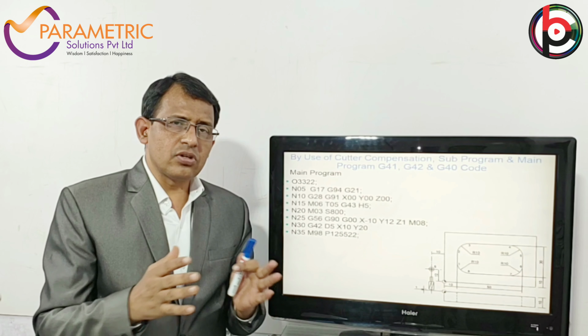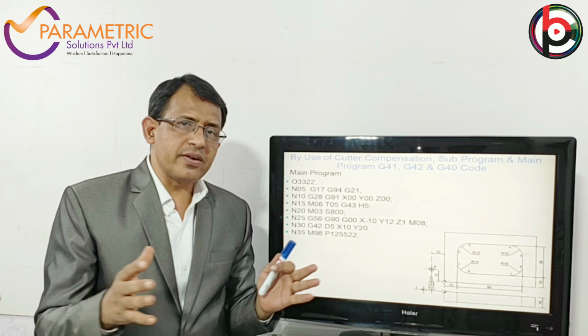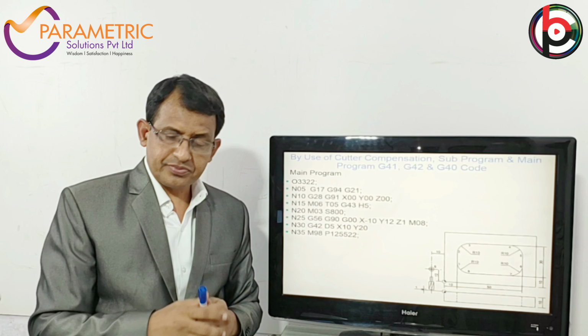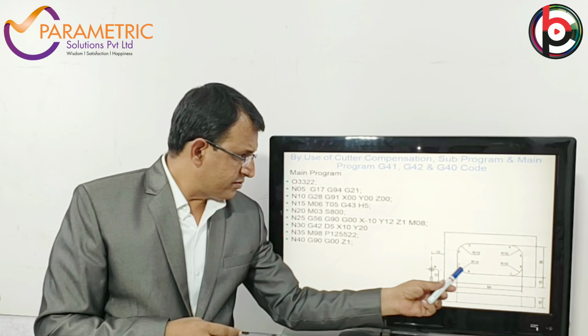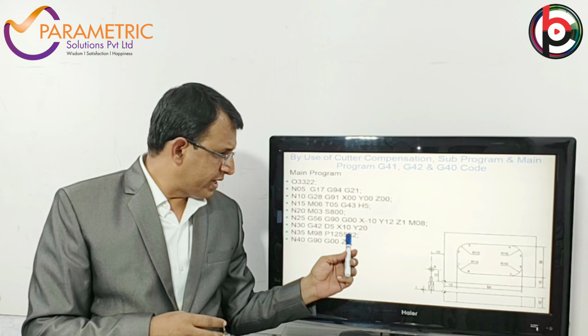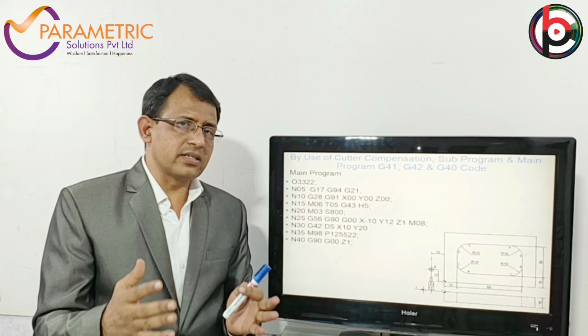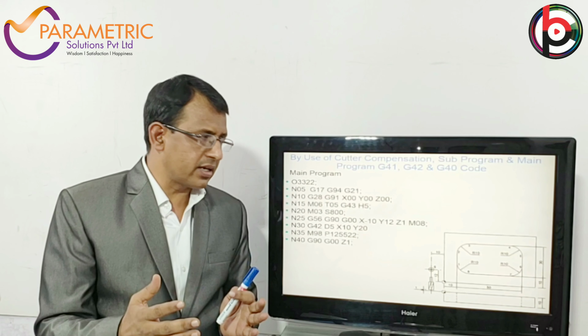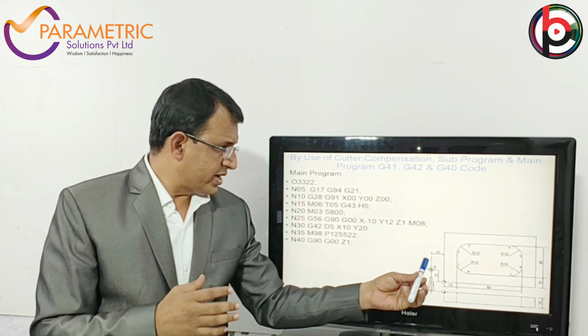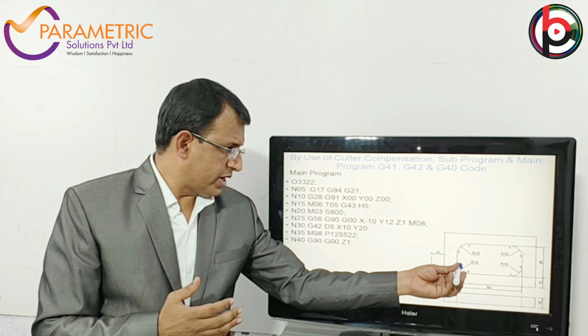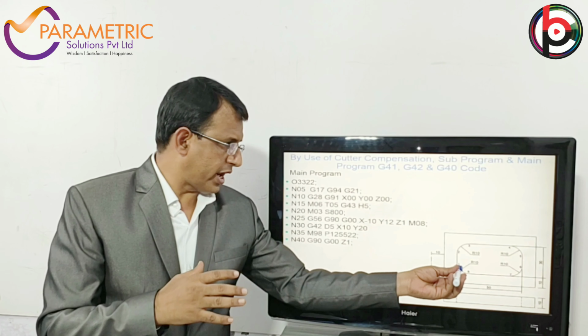The use of this is that you can reduce the length of the program into one statement itself. After the 12 repetitions, this is also called a canned cycle. And after that, at the last point, M99 ends the subprogram.